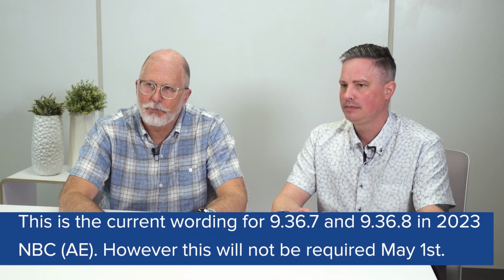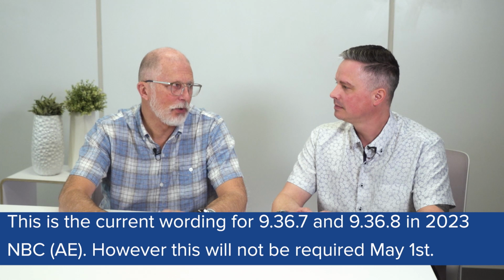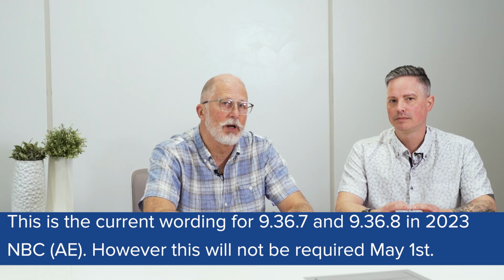So then with the prescriptive requirements, my question is, what do I need to do for compliance when the code takes effect? When we comply with 936.8 tiered prescriptive, the change that we're going to see is HRVs will become mandatory, even at Tier 1. So Tier 1 takes us back into 936.2 through 4 for those effective values in our walls and roofs, but it removes the requirement for those tables. We now have to meet the with HRV table, not the without HRV table.